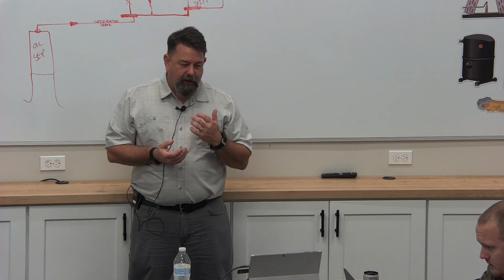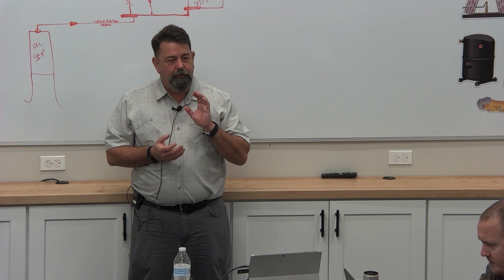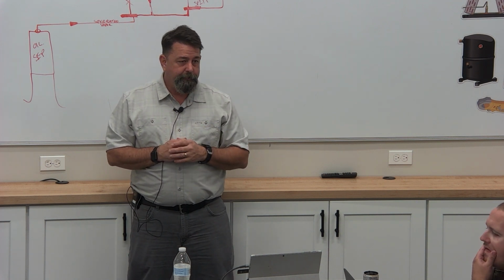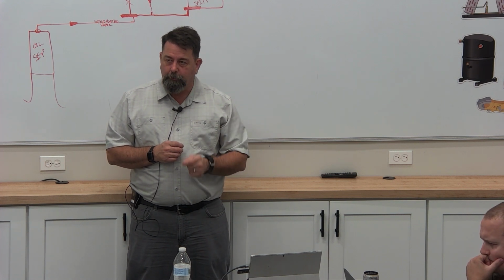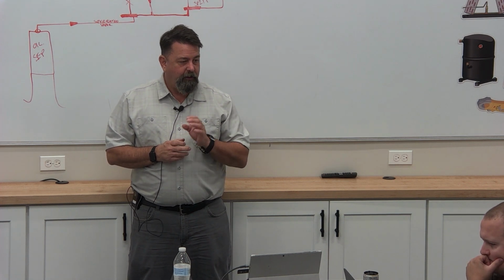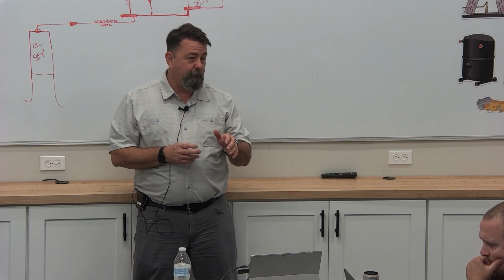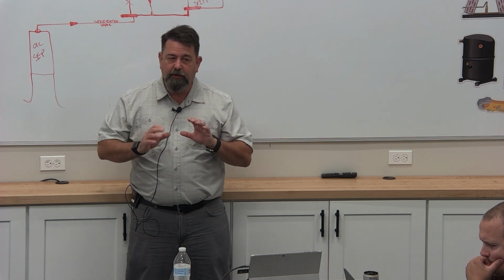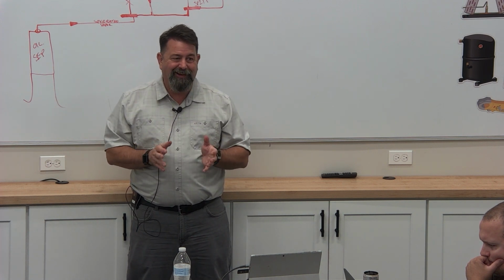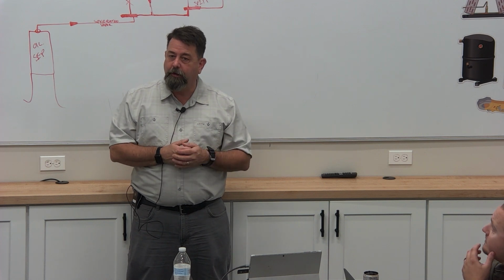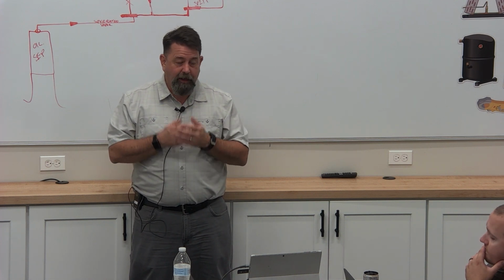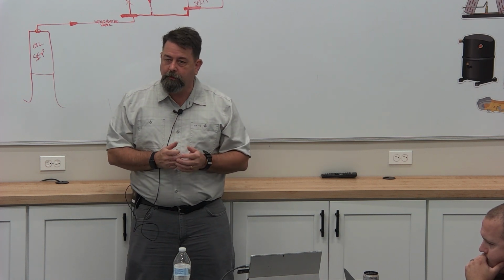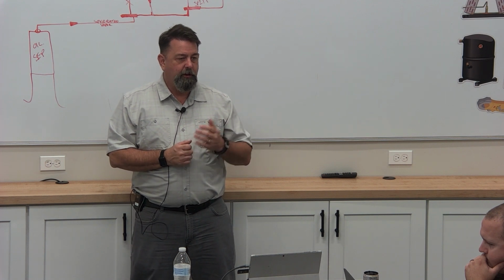What does that mean? That means the most important piece to this is the blade. We need to match the fan blade exactly, right? If we get a fan blade that's rated to the same thing, but one had 5 blades, this one has 4, but it has deeper pitch, we think that's going to be the same. It's not going to be the same, right? My pressure's going to be different, which means I'm going to move through that coil differently. It will move the exact same CFM in a laboratory, but in that case, it's not going to, okay? So we want to go back with the same blade.